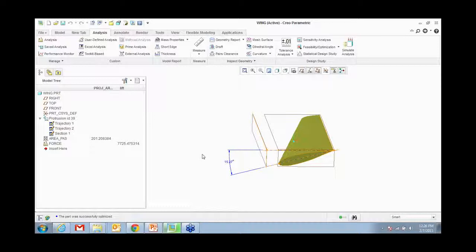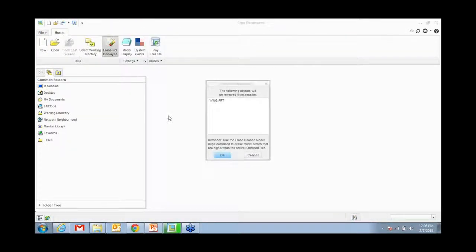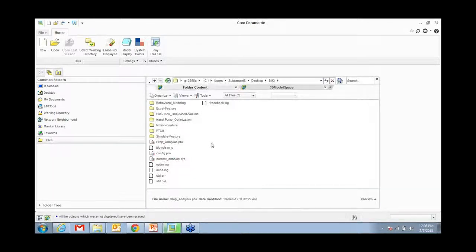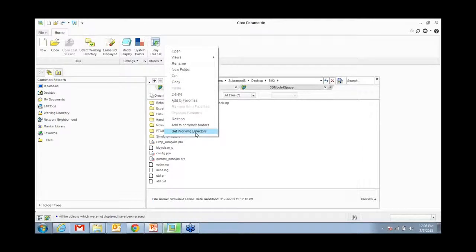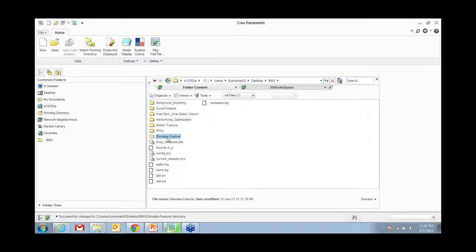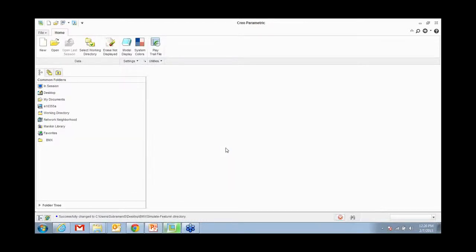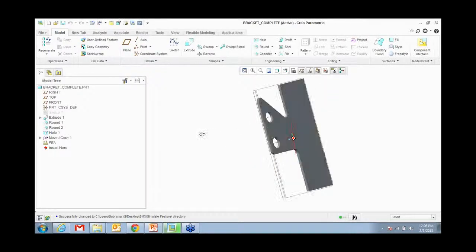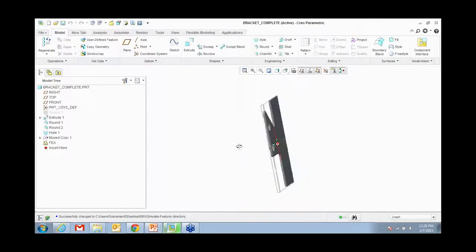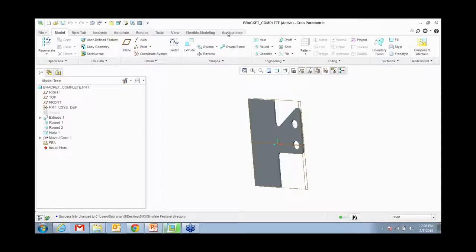So it's going to give me a nice little graph and tell me that, okay, here's my first level of optimization. And it tells me that that's the value that I got. So you go close it, confirm it. You see, that's the max lift we're hitting at 15.27. All right. So this was working with Excel and Pro E to do analysis.